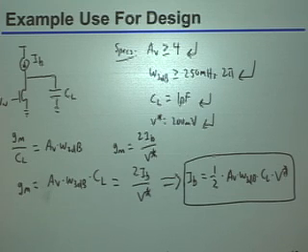Okay? So again, notice the power of this is that once you specify these things, you immediately know how much current this is supposed to take, right? No complicated IV curve lookups or anything like that. You immediately know this is how much current this circuit is going to have to take, okay?